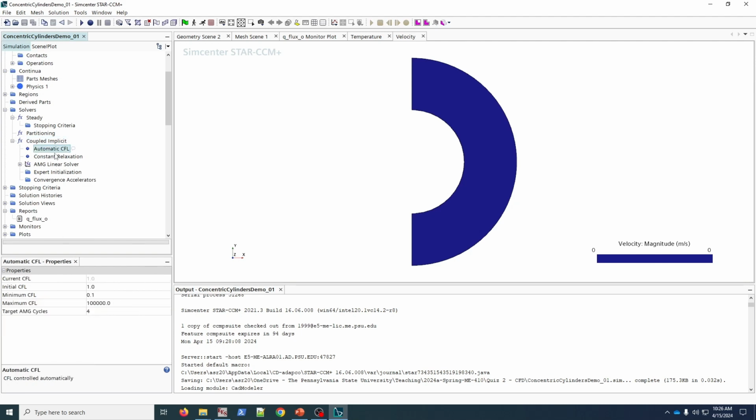So this one is a CFL parameter, and it basically says for each iteration in this steady state solve, how far or how many cells out will be considered when it's calculating the interactions between quantities in the neighboring cells. So the default values here, in my opinion, go a little high. Let's cap this at like 100. So essentially, it'll initialize with a conservative CFL value of 1. If for some reason it wants to go down because it's taking a long time to make each individual iteration, it will go down to 0.1, and then it can potentially go up to, well, let's add to 500 here.